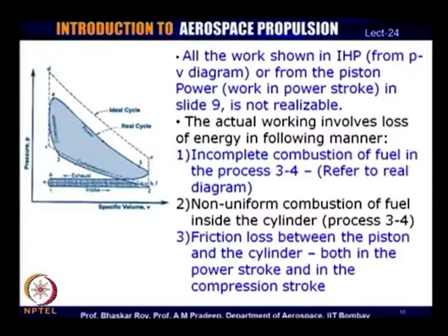And then, larger the engine size, that is length and diameter, more is the surface of the friction loss, and as a result the higher are the losses. Larger the cylinder size, more are the heat losses through its cylinder surfaces. So, those are the other losses that start coming into the picture now.